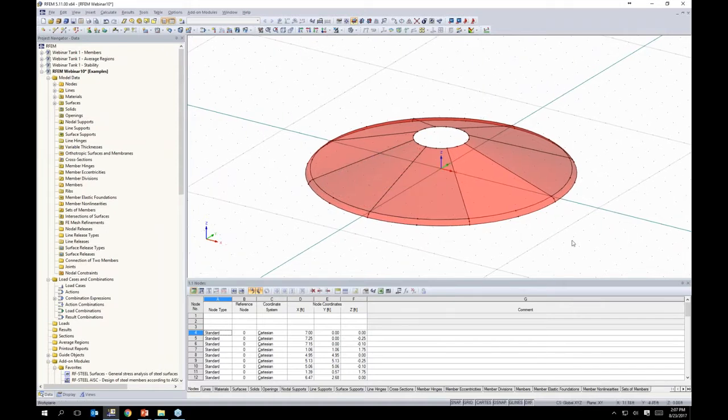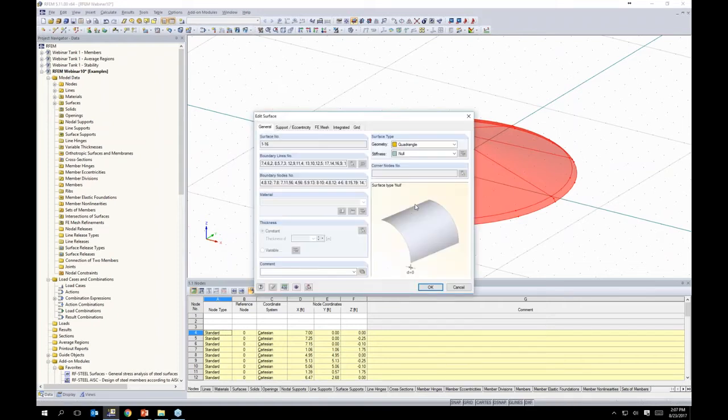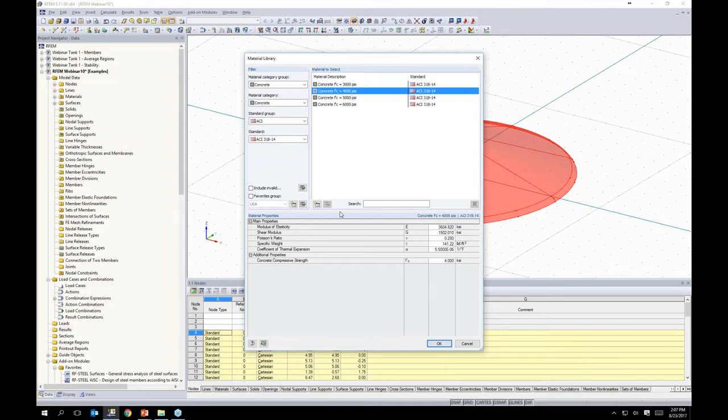They are highlighted red right now, and the reason why is because if I highlight all of these surfaces and double click to edit them, the stiffness is set to null, and that's simply because we didn't have a template to choose from when we were in that expanded settings. That's easy enough to change by using this drop down to change this to a standard stiffness, and we'll define our first material within the program. So we have a couple default materials, but I want to move forward with stainless steel for today's structure.